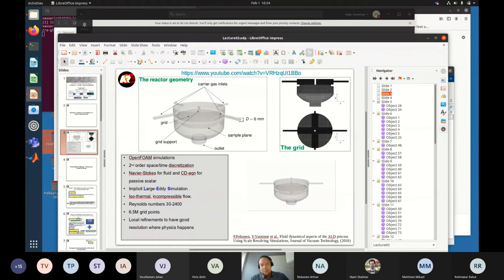It's also assumed that these are gases, but we assume they are isothermal, temperature is constant, and then the incompressible assumption is typically good. Low Mach number, low speed flow, and this air is essentially incompressible, that you have in normal room air conditions, for example. You have small density variations, but those are maybe like 1,000th of the average value, so you can neglect that with good accuracy.